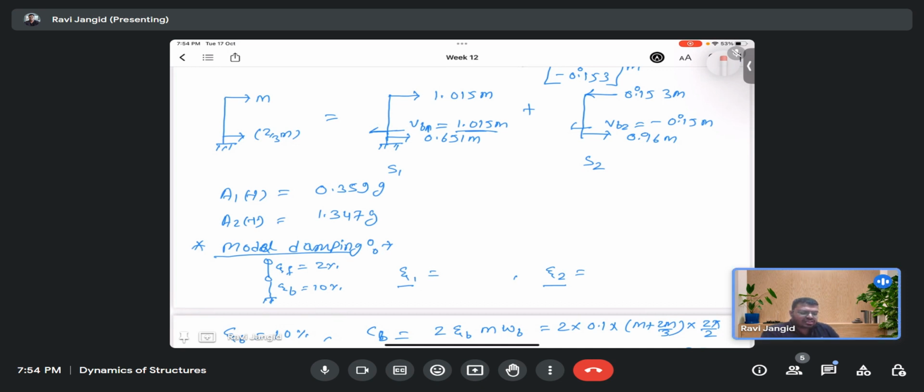Then TD by TN, that is what you are calculating. Here in both cases we have the free vibration case, right? In both cases your pulse shape doesn't affect, so you will get I by m omega n directly. For free vibration you can directly get u(t) equal to I by m omega n sine omega t. If t is less than TD, in Duhamel's integral, we have derived the response. You can just see it in the problem solving session.